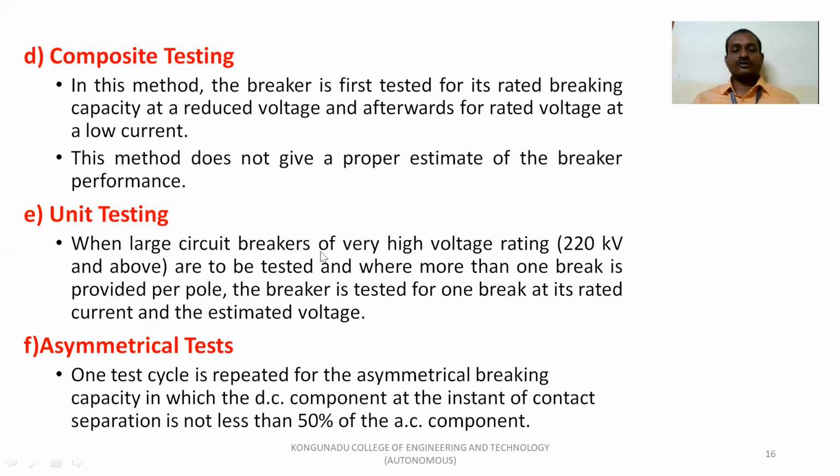The next method is unit testing. When large circuit breakers of very high voltage rating, 220 kV and above, are to be tested, and where more than one break is provided per pole, we test the very large rating circuit breaker this way.